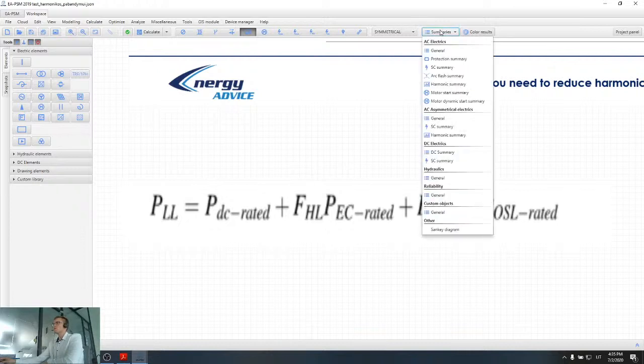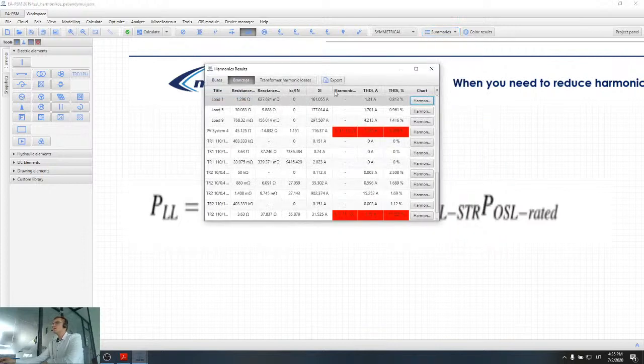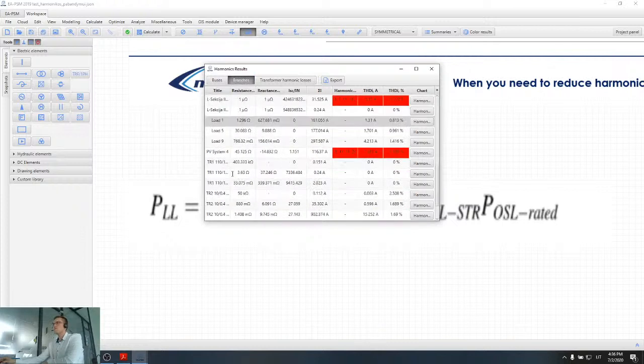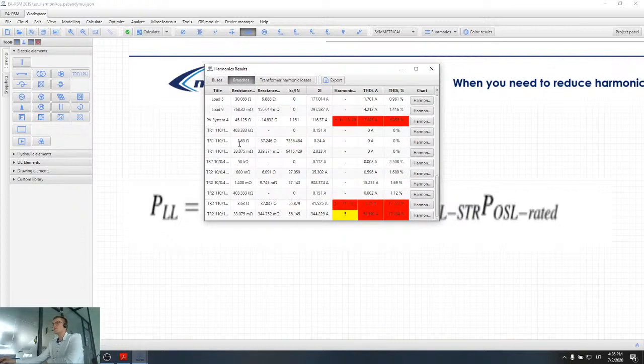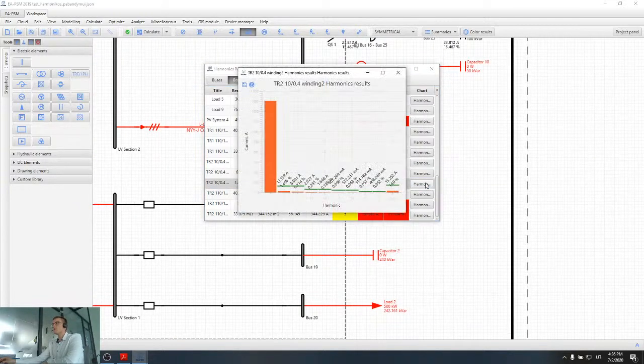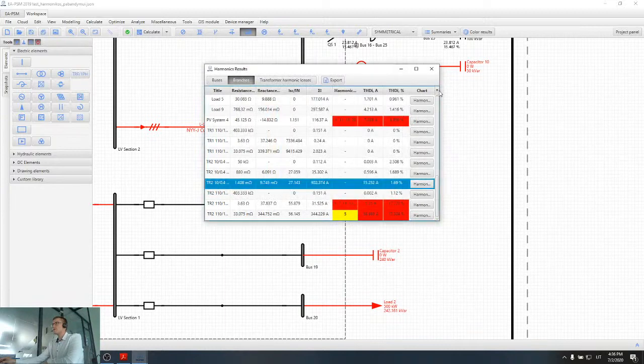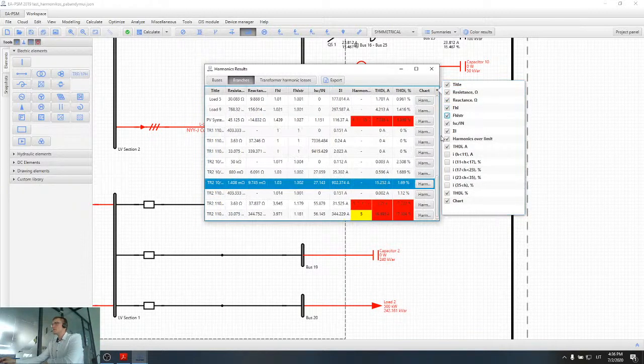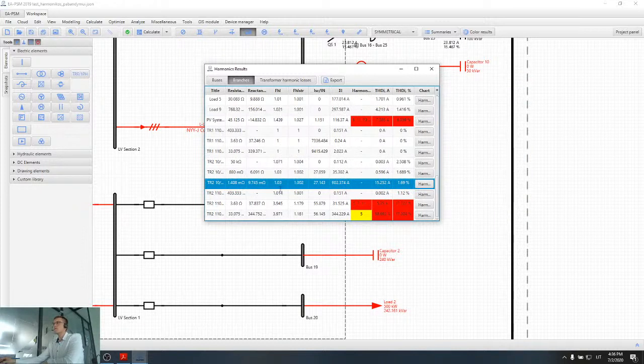If I open the summary table, let's go to Harmonic Summary, and take branches, let's say any cable or transformer. Okay, maybe let's take a transformer, since today we most commonly use the transformer for our analysis. I can add those factors to the table, and I can see that with these particular harmonics flowing in the network, losses in the transformer are only about 3% bigger than normal.